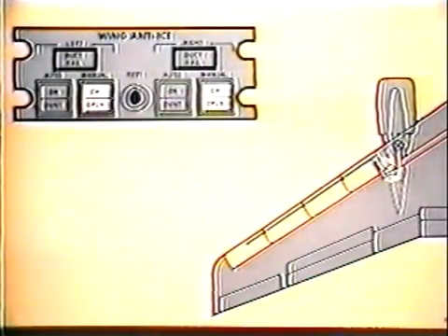With the manual switch latched, on is illuminated and the wing anti-ice valve is electrically armed and will open when pneumatic pressure is available. The open light illuminates when the valve is open. The valve will remain open in the manual mode regardless of the temperature in the slats.